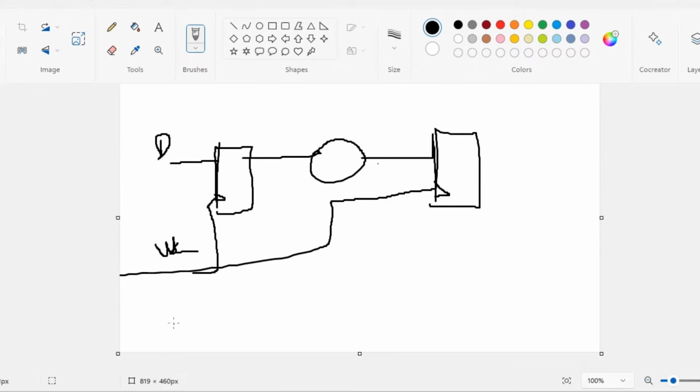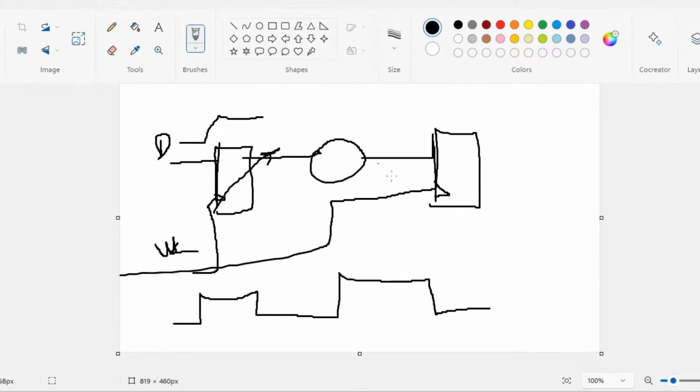Do you know how the flip flop works, right? All people. So let me explain. Whenever the positive edge of the clock comes here, then the data will go from here to here. Then data will come here, and here it will check for the setup time. Okay, at this edge we are checking for the setup time.